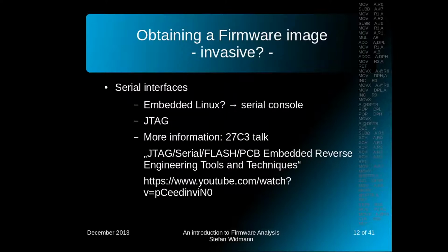We'll search for serial interfaces. Sometimes they are accessible without opening the device, sometimes not. Do we have an embedded Linux system? Yeah, we search for a serial console. Maybe we have to use JTAG. There was a very good talk on JTAG, serial, flash, and so on. So I've included a link here. So, still no firmware? Get your screwdriver, let's void warranties.